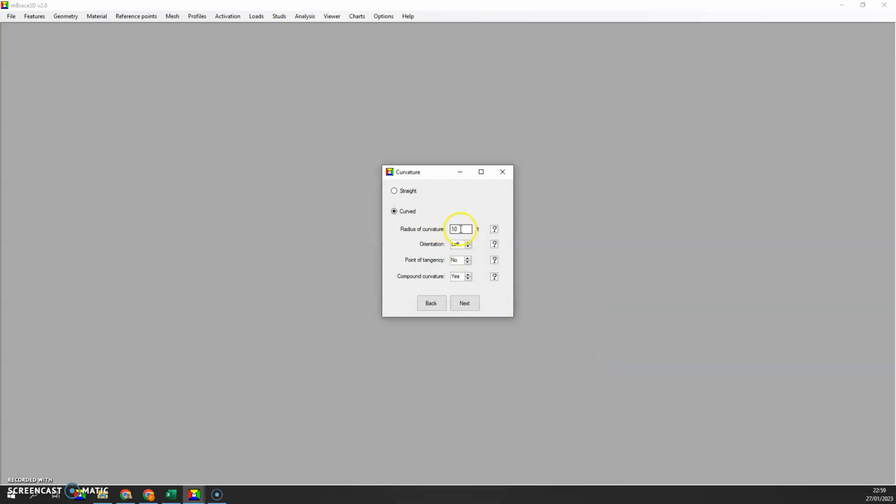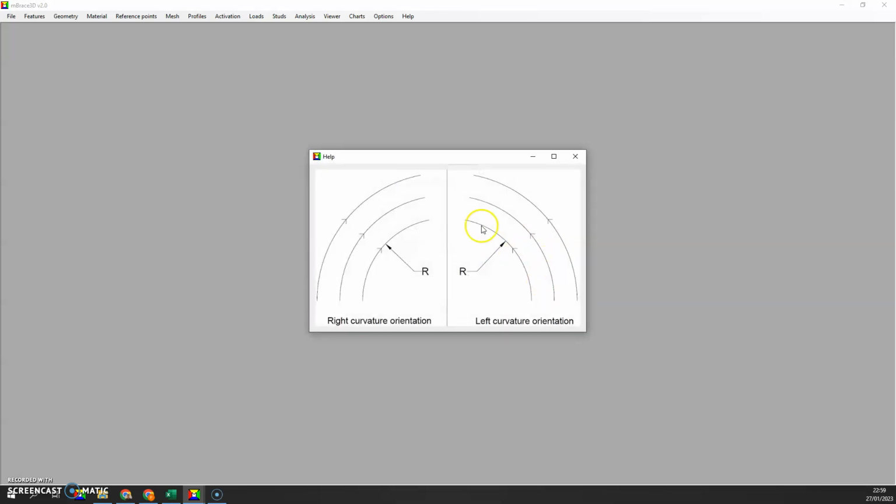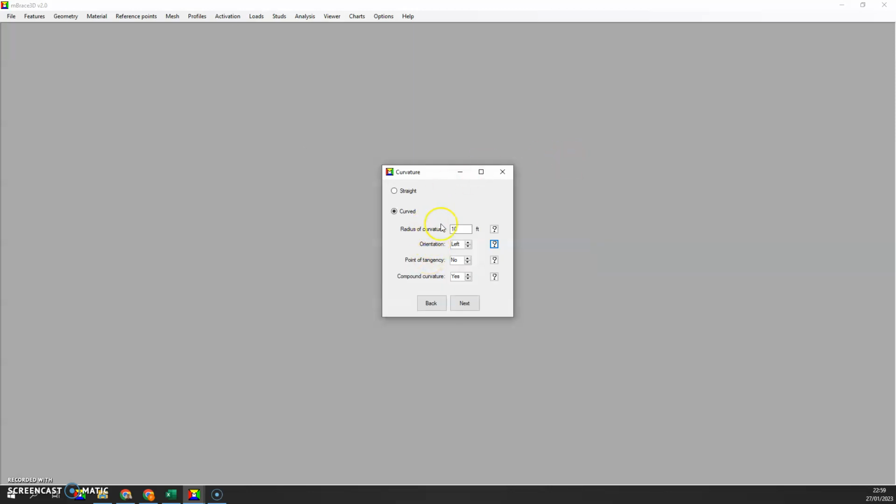The radius of curvature here, you see, it's extremely tight. It's just 10 feet. And the limitation usually of this, if you're not selecting this compound curvature option, is to have a subtended angle which is limited to 90 degrees. If you want to go half circle, you would need to check yes here. You need to select yes for the compound curvature.